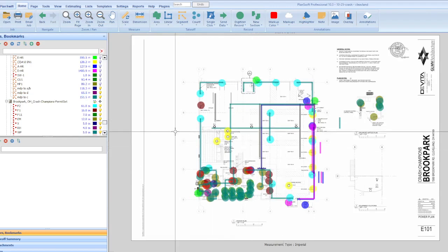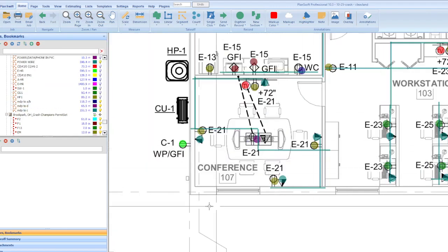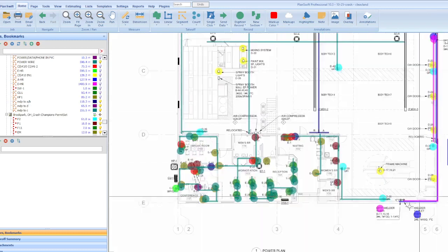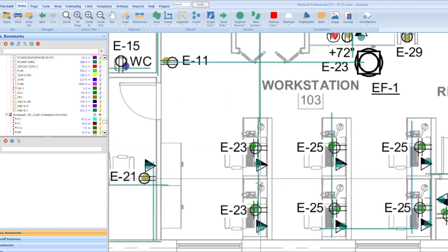Okay, so the basics of electrical estimating is having a real good counting tool and practicing on your conduit lengths. Now, you may get some plans that already have all the lines drawn and you just follow those, but when you don't, just know that on the power plan, this is telling you that these two outlets are going to the same position in the panel, so the power feeder can run together.